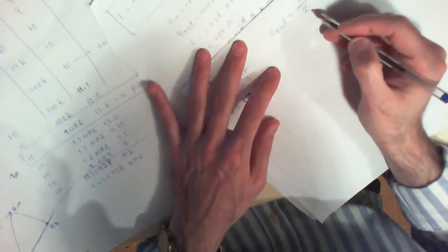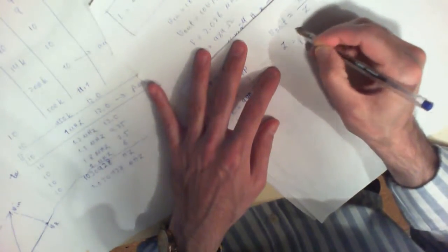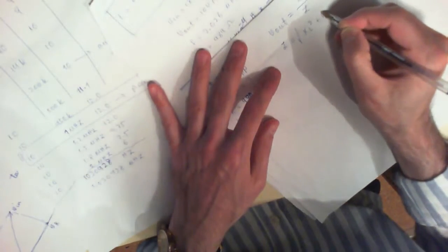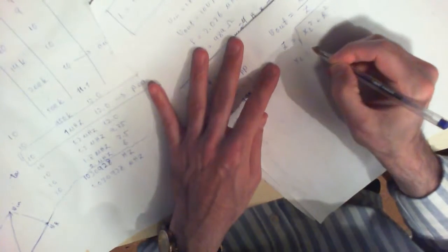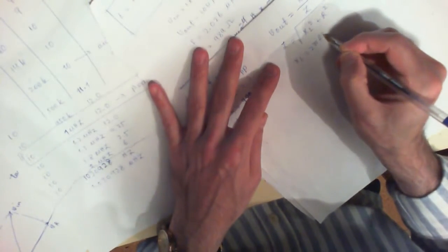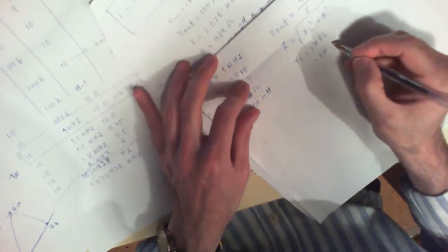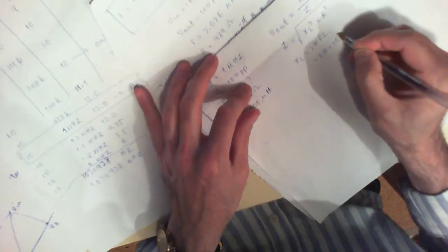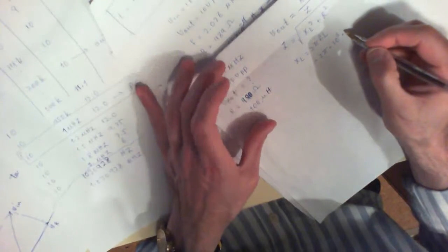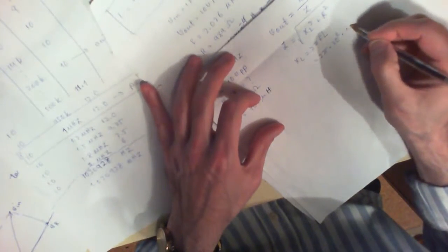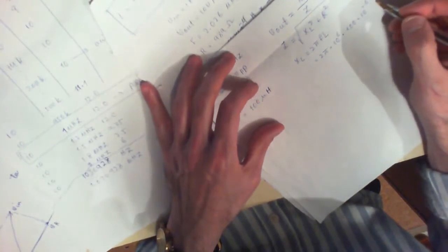The only thing that you need to calculate is your impedance, which is the square root of X of L squared plus R squared, and for that you need X of L. So X of L is equal to 2 pi FL, which is 2 pi times the frequency, 1 megahertz, 10 raised to the power 6 hertz, times the inductance, 100 microhenry, 100 into 10 raised to the power negative 6 Henry.